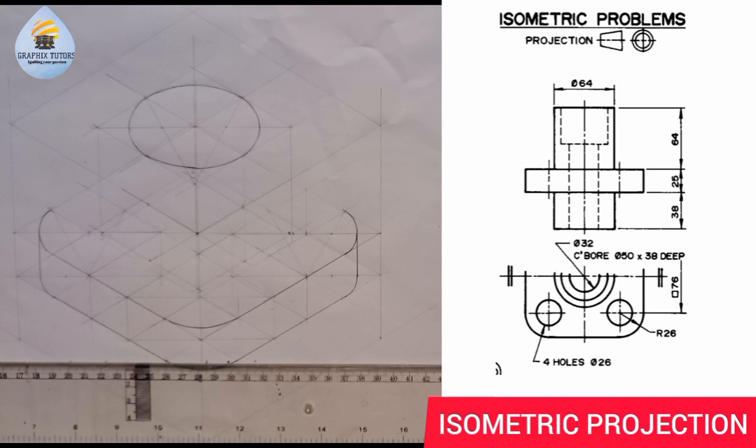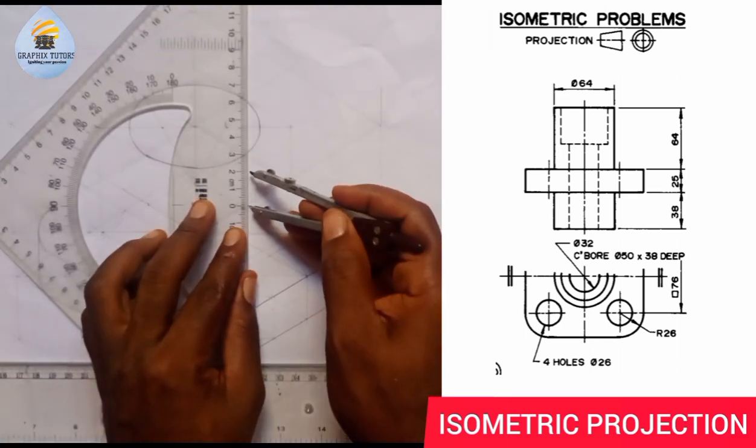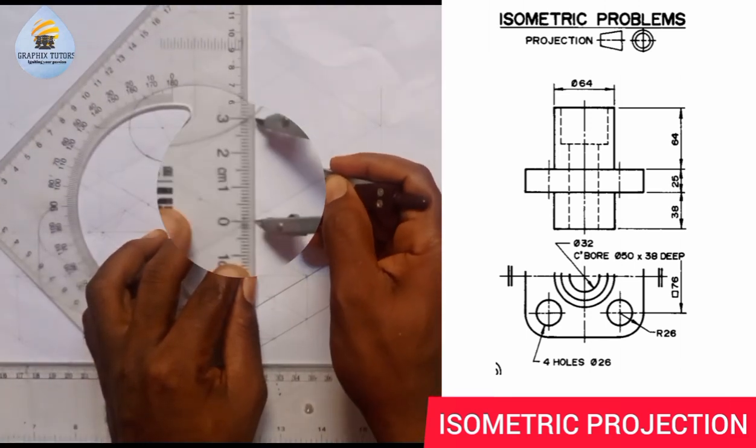Now the internal one, can we see what the internal one is? You can actually check it from this part here. Since we're having a set 32, we're giving it to be what? 32. So the inner circle below here is given to be 32 diameter, and the ball here is given to be what? Given to be 60. Can you see that? So what I'm going to do is I'll take half of 60, which will be 30. I'll measure it on my meter rule, 0 to 30.